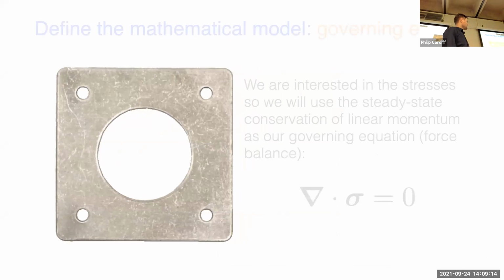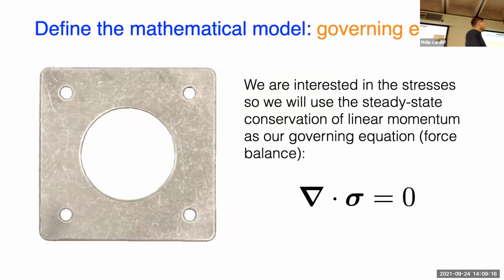Okay, so let's start with the governing equation. In this case, we're interested in calculating the stresses in the part. So for any problems calculating stresses in solids, we'll always start with the conservation of linear momentum. So that's this equation in steady state form.